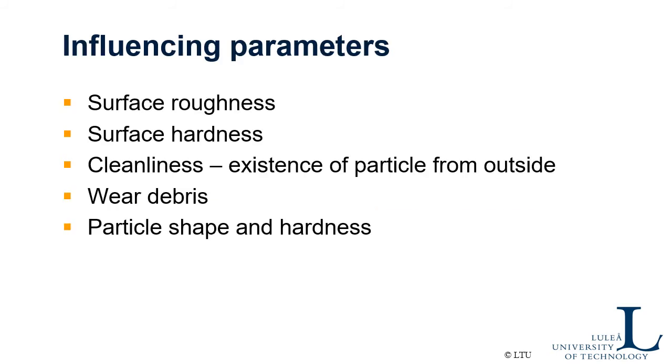In this case, surface roughness is an important parameter, of course, especially if a rough, hard surface comes into contact with a smooth, soft surface. So hardness itself is also important here. The harder the material is, the less risk for abrasive wear.